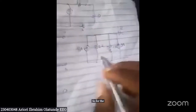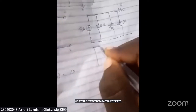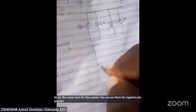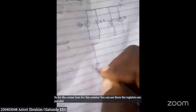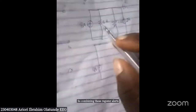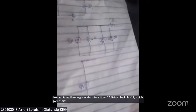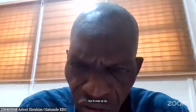So for the current over here, I can see the resistors are parallel. Combining this resistor, I have 4 times 12 divided by 4 plus 12, which equals 48 over 16, which equals 3 ohms.